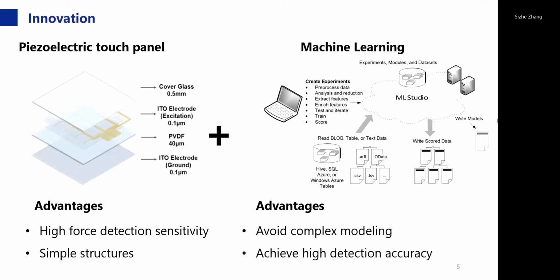To satisfy this urgent need, the piezoelectric touch panel in our previous work is used for detecting force touch events. The piezoelectric touch panel is made up of 4 layers: glass substrate, patterned top ITO electrodes, PVDF force sensing layer, and ITO ground electrode. The sensing ITO is etched as a 4x4 matrix, which contains 16 square-shaped elements. An optical clear adhesive is used to laminate layers.